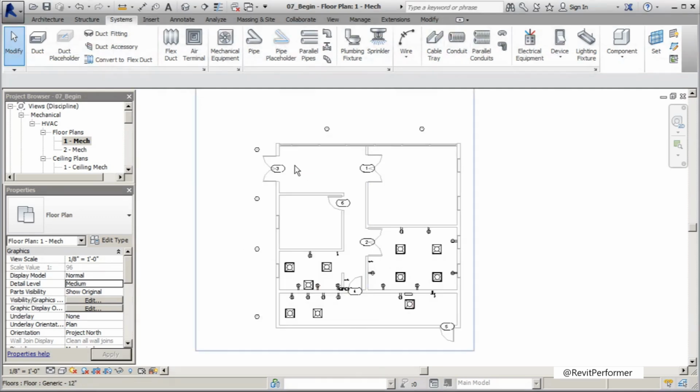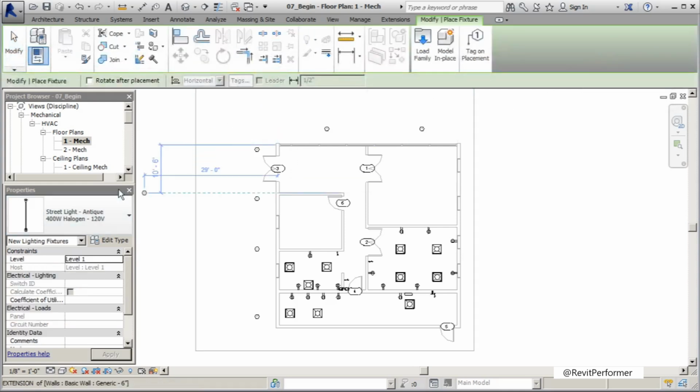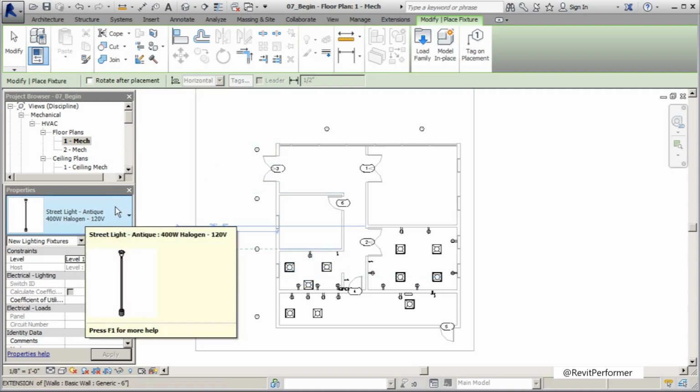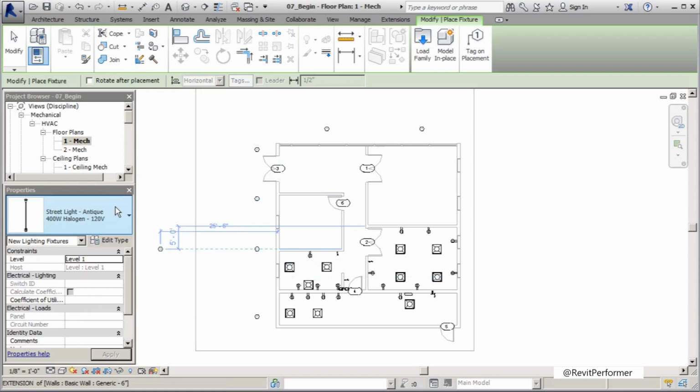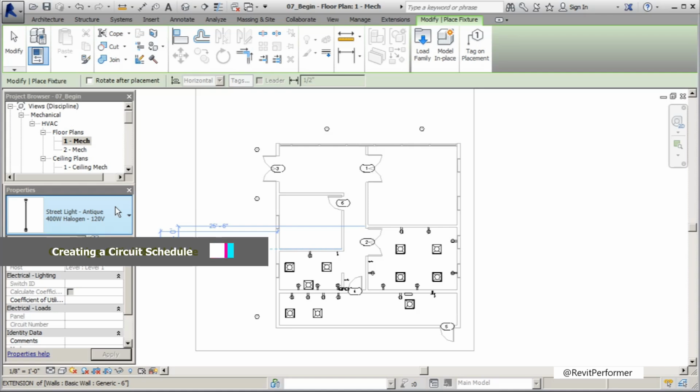Let's take a similar approach and a green approach to what we can do on the inside of our office here. So up to this point, we've been using a lot of the 2x2 troffer lights or the 2x2 parabolic lights. Let's use a different lighting, a different switch, and let's finish out this office suite. So I'm going to go back to lighting fixtures again. And for this one, instead of using the parabolic, we're going to use some recessed can lights. They'll be used to illuminate our lobby area as well as the main hallway during times when this space is unoccupied, so we don't have a totally dark space. That way, if anyone does come in after hours, it's lit and it looks somewhat occupied from the street.